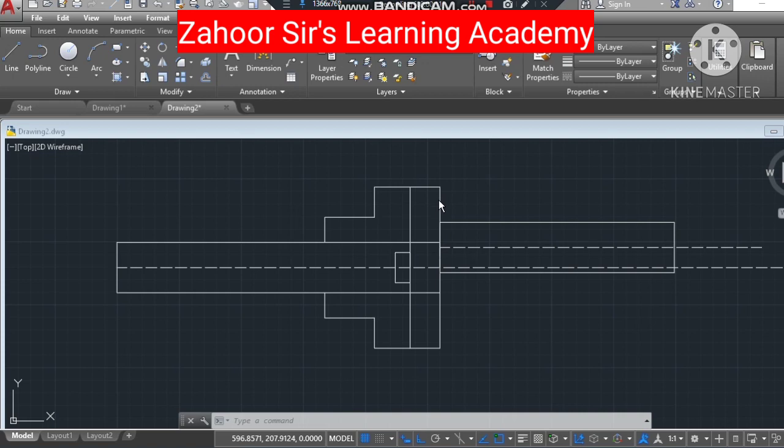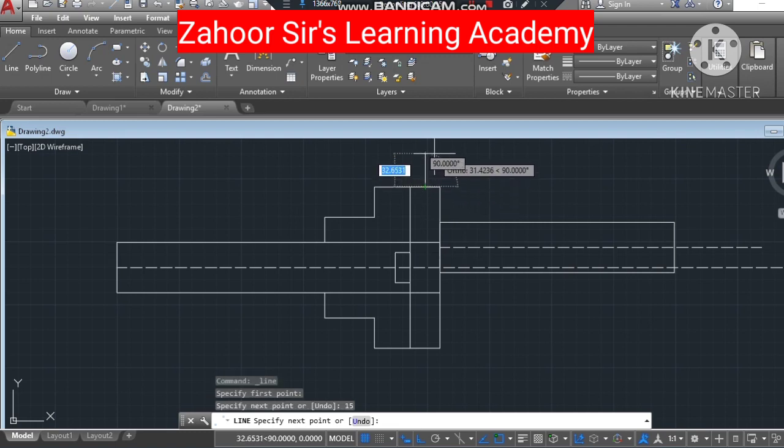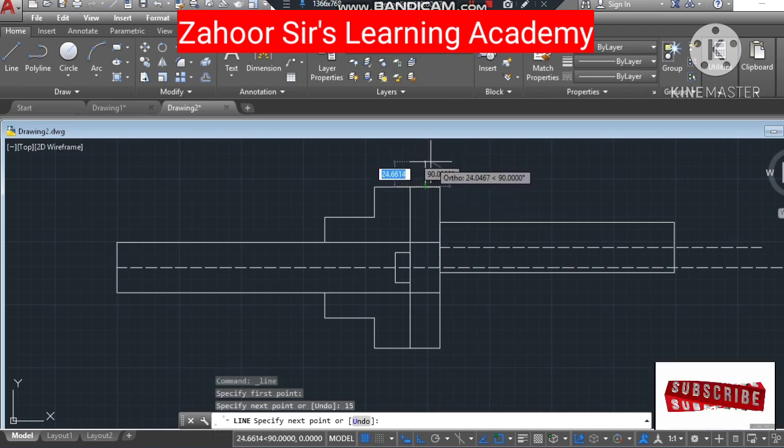We also have to draw similar things as we have drawn on this end, that is the flange and the hub portion. So let me show you how we can draw that portion. I will pick a line again. From this point, I'll go 15 mm on this end. So I'll write 15 mm, then press enter, then I'll go up because the two center lines are 20 mm apart.